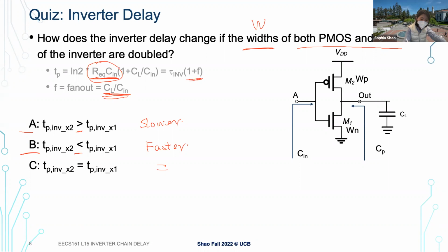So we abstract this component into tau, and this is actually a size independent parameter. The reason it is size independent, if you think about the relationship between resistance and capacitance, right? With a wider width, our resistance gets smaller, right? We have a wider channel, we can flow faster.